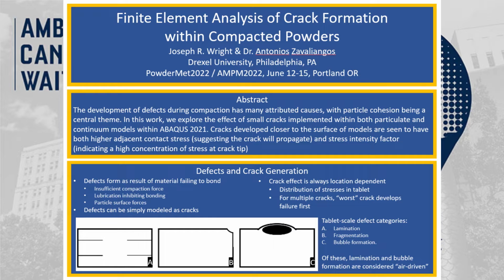Since compaction forces two or more particles together, we can assume that the development of defects is attributable to the material failing to bond. Insufficient compaction force, lubrication on particles, or contamination within the powder can all prevent bonding between particles. To simply model them, these particle-scale defects can be considered small cracks, with the development of tablet or large-scale defects dependent on the location and severity of cracking.